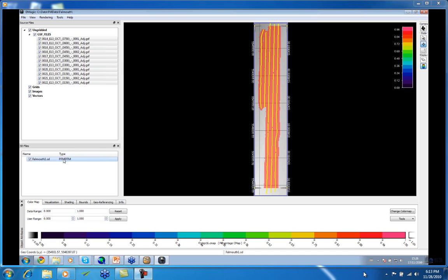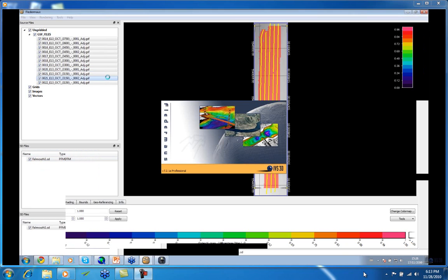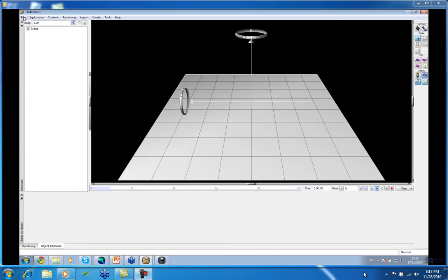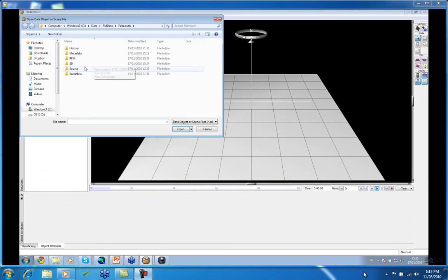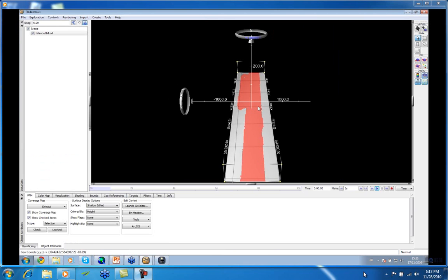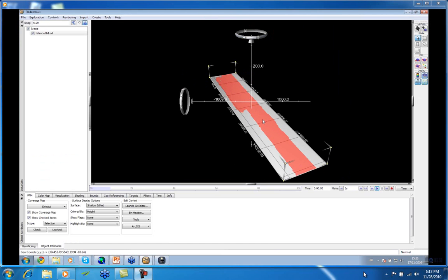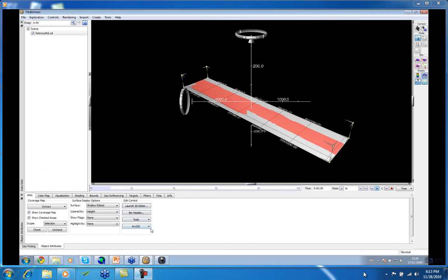Now, to look at this and to run this, we'll go into Fledermaus. You can double-click on it, but I'll just open up the SD file. There's Falmouth 1. So this is our PFM now in 3D, just with the bounding area, and just to show, we have a georeferencing here as UTM zone 30 as before.